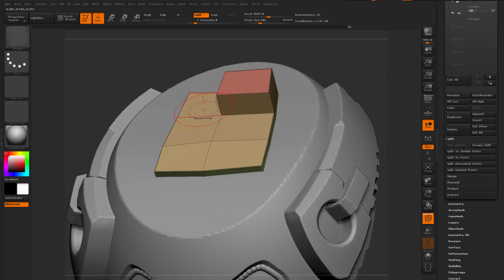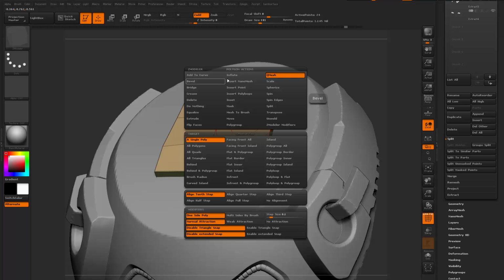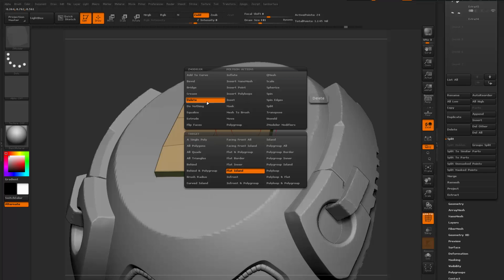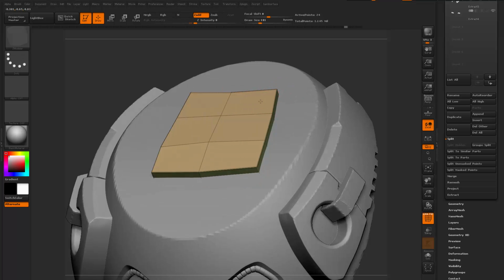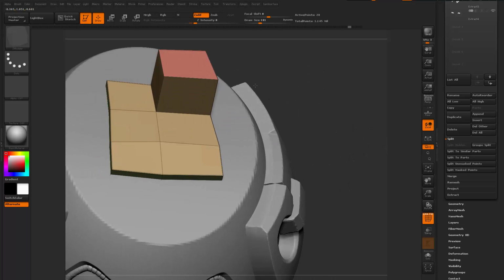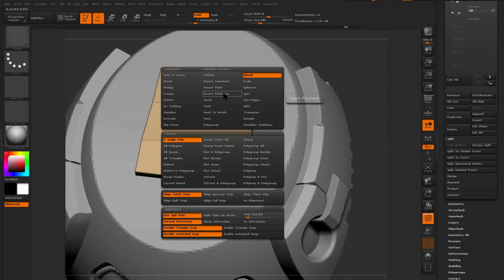Okay. So you can extrude things out like this. You can add an edge loop when you drag on the edge. You can move points. What's actually happening is when you hover your cursor on any face and hold down space, you will see all the actions you can apply on that face, like delete, for example, or bevel it, or QMesh, which is more or less like a smart extrusion. And that is the action here.